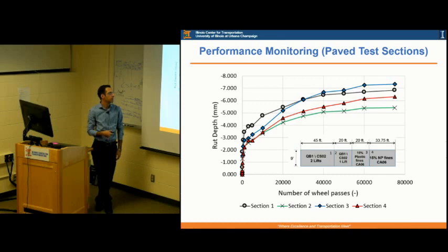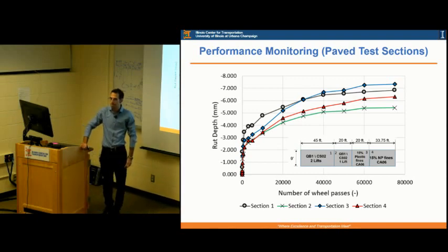What is the composition again between section 2 and section 4? So in these sections, you have 21 inches of the material that we are investigating on top of the CBR1 subgrade, topped with 3 inches of capping material, which is a dense graded base material, and then topped with 4 inches of HMA on the surface. So for the QB product, QB plus cement on what? No, this has no cement. Yeah, these are the unbound applications. Just QB? Yes. Which section are you talking about?